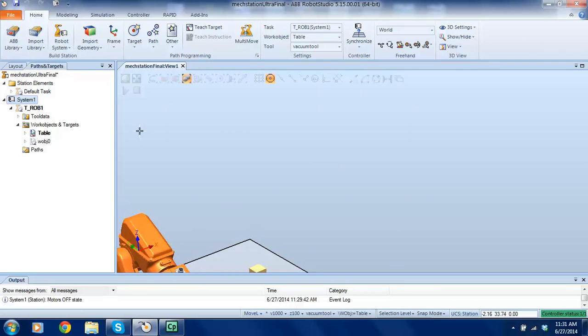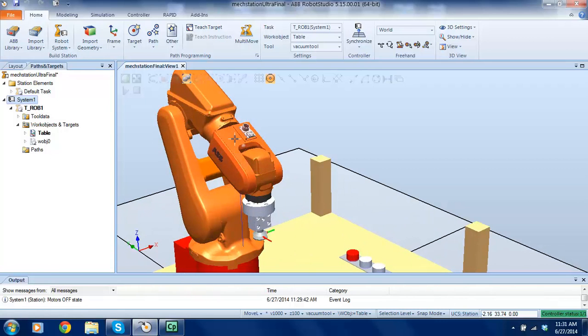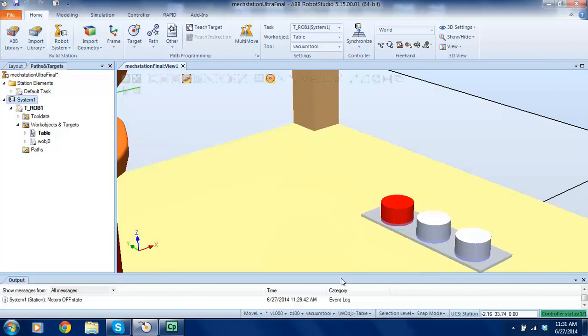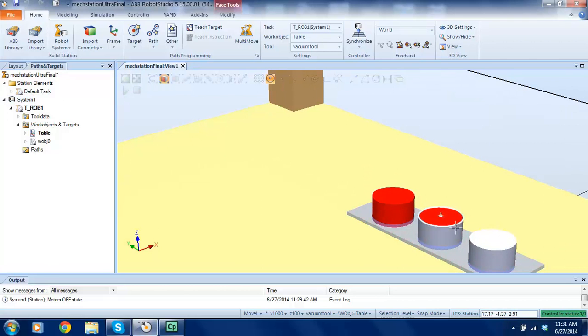Now what else do I want to show you? Also, there's an awful lot of lines and curves and geometry that we need to select. On the top of this frame here, if you want to just select a surface, I can select a surface. If I want to select an object, I can select an object, and so on. Typically it's going to be just surface, and then I can have this. This is similar to the snap in AutoCAD. So at the moment it snaps to the center points, like so. I don't know if you can see that.